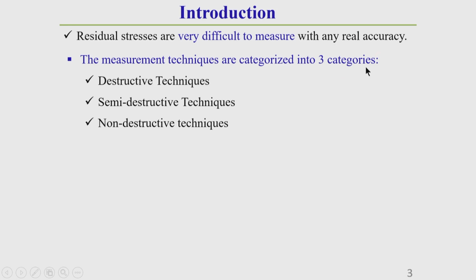Now, we know that residual stresses are very difficult to measure, because this is a locked-in stress. We have to remove that lock first, and only then can we measure that residual stress. That is why there are different types of measuring techniques. Though these measuring techniques are there, it is very difficult to measure with any real accuracy. This you should keep in mind.